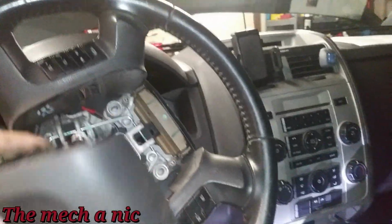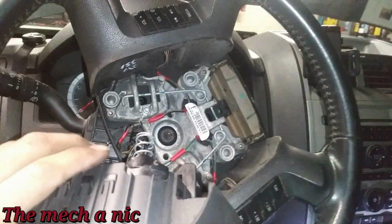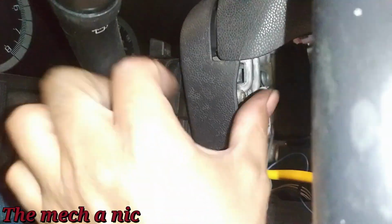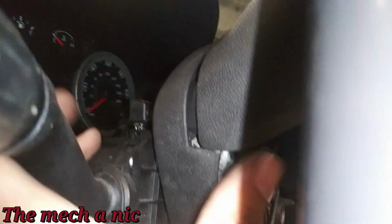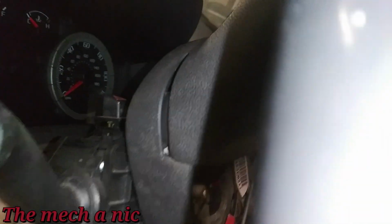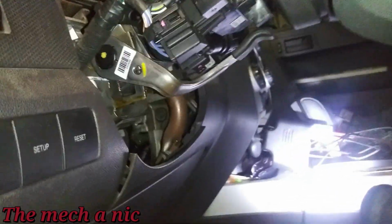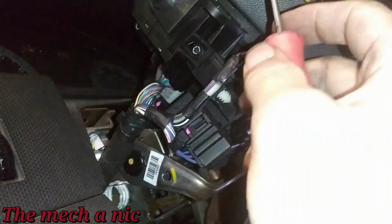So number two, you see how I got the steering wheel turned sideways? That's what I do, is I turn the steering wheel sideways, and then this back panel right here actually pops off. You see it, how it pops off like that? And you just kind of work it all the way around, and eventually it's going to pop off. Not a lot, but it's going to give you enough slack. Okay, once you get this back panel popped off, grab a small 90-degree angle pick like this, and